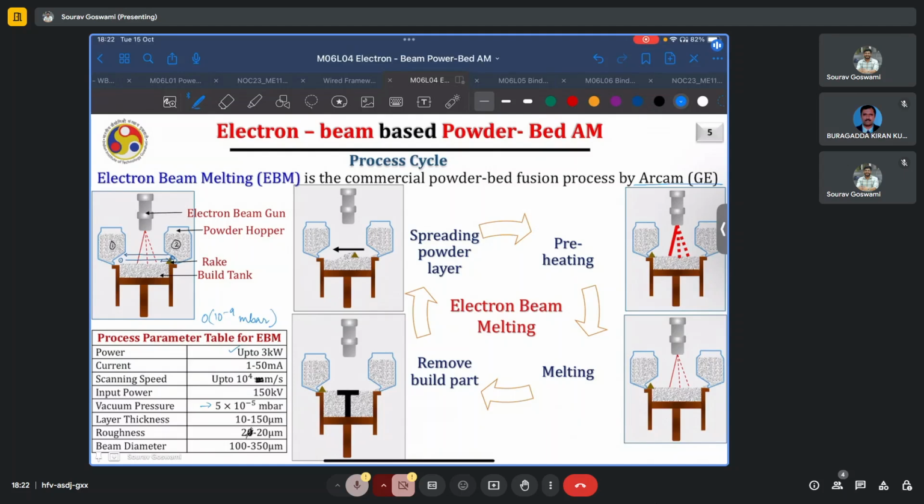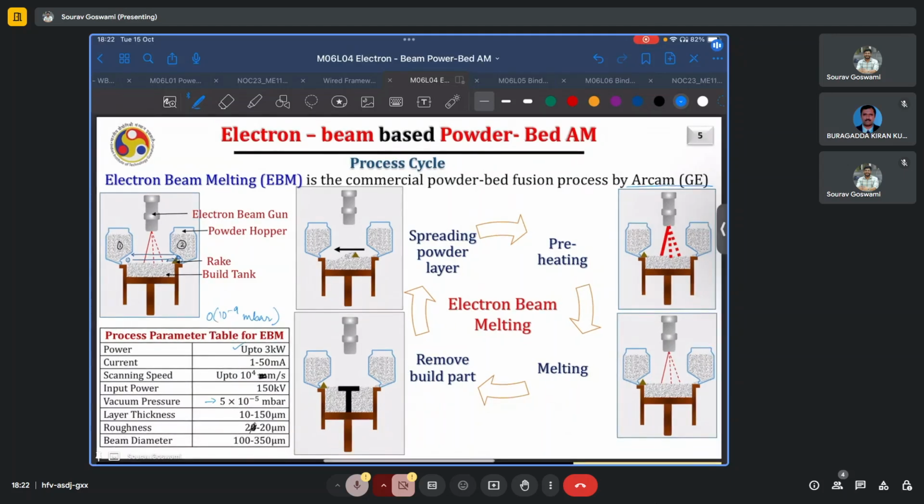Of course, the other way is to decrease the electron flux, in which case the beam dia can still be reduced. But in that case, there simply might not be enough energy in the incident beam to build the part or to melt the metal powders. Thus, there is a naturally imposed floor on the smallest beam diameter for such processes.